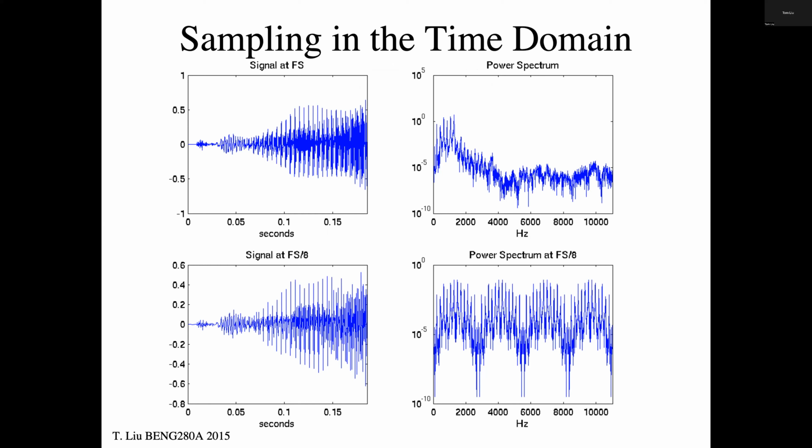I think we were looking at this slide, which was a time domain signal. And this could be something that you measure with a radio frequency antenna, doing an NMR experiment or an NMR image. So you elicit a signal from the patient, and your antenna picks up this signal, and it's voltage versus time. And we're looking in general here. We're going to look at the criteria for sampling this signal adequately.